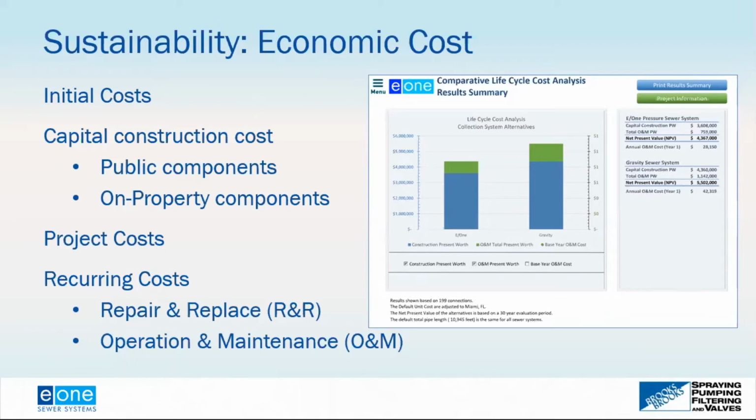And it's not uncommon, because the cost will be similar, to not include that when you're doing a life cycle cost analysis. Because if you're looking at two alternatives and one component is the same, there's no harm in eliminating common elements. Keep in mind that you're doing that evaluation just to compare A versus B. You're not doing that evaluation to try to determine the true project cost or the cost of the overall project. If you really want to get a good estimate on what this infrastructure project is going to cost, you typically would want to include all the costs, including those project construction administration costs.